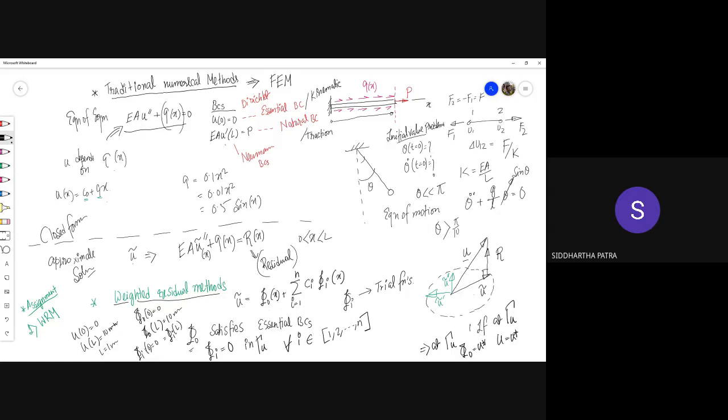Right now with this example, one end is gamma u, the other end is gamma t. So this one is gamma u, the kinematic boundary condition, and this one is the traction boundary condition, hence gamma t. But just take an example where both are gamma u's. In that case, phi 0 takes care of the essential boundary condition, but phi i's would be 0 at both the boundaries.